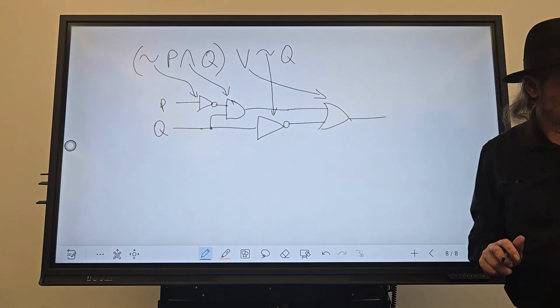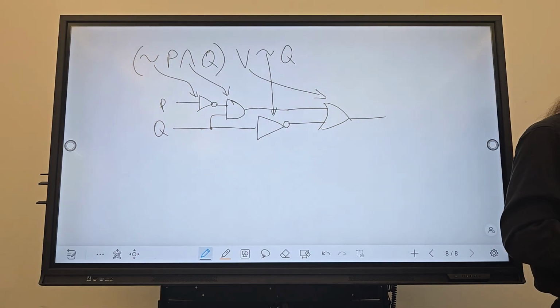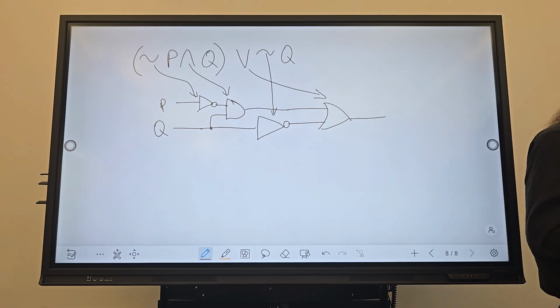So you start with the OR because it's the lowest priority and is the last operation done. Place it to the extreme right of the diagram. Continue working backward in the order of operations to get the gates and their connections from right to left.